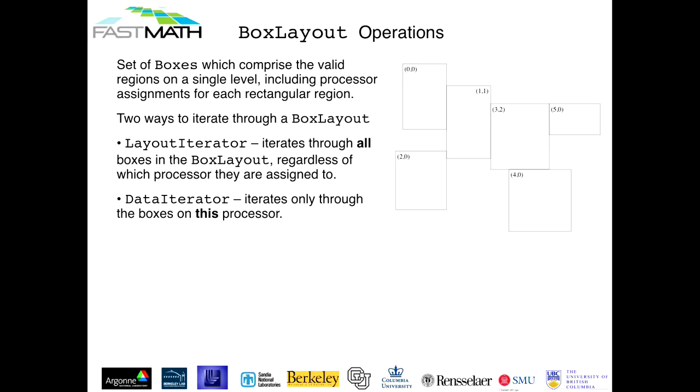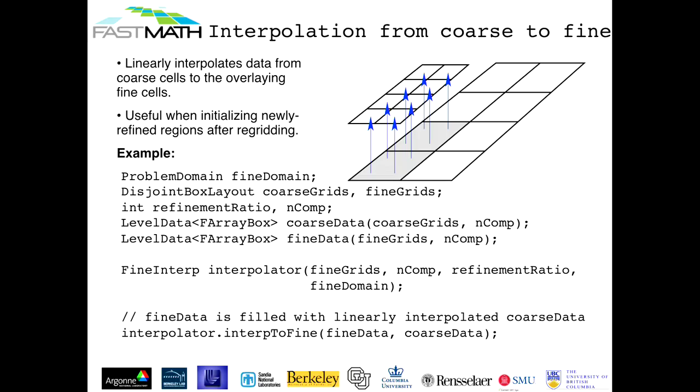We also do one level finer than that, but that's not in this particular tutorial, where you break boxes up into smaller things. AMR applications, you have interpolation from coarse to fine. So we have the fine interp. Fine interp handles things like bringing a solution from a coarser grid up to a finer grid. So you'll use this for things like the multigrid algorithm, where you need to take a correction computed at the coarser grid and bring it up to the fine grid and use it as a correction.